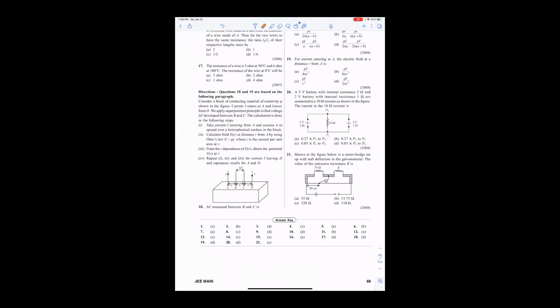So again, here, Wheatstone balance, Wheatstone concept, meter bridge. 55 R, this is 20, this will be 80. So 55 by 20 is equal to R by 80 when it is balanced. So R is equal to 55 into 80 by 20, which is 4. So 220 ohms. Right?